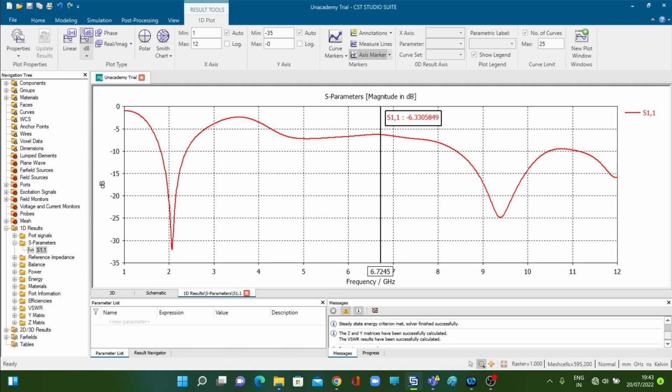Now, if I would have selected the number of samples instead of 30 to be 50, then these steps would have become gradual. I mean, you would have got a plain line here like this. See, like this. You would have got a plain line here. So that you can do, that you can optimize, you can increase the number of steps. This effect you will obtain. The computation time will be more, but the graph will be much more gradual. So that is the difference. That is the only difference which we have.